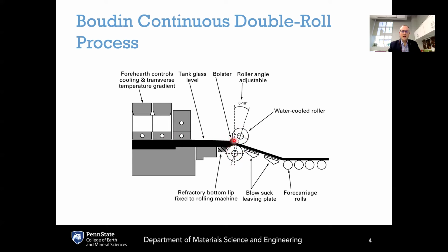And the molten glass passes through the rollers, and this gives you pretty good thickness control where you can adjust the spacing between the rollers to adjust the desired thickness of the glass. And then you've got a fairly uniform thickness sheet of glass that comes out the other side. The glass comes onto rollers and then gets pulled into latter parts of the process.